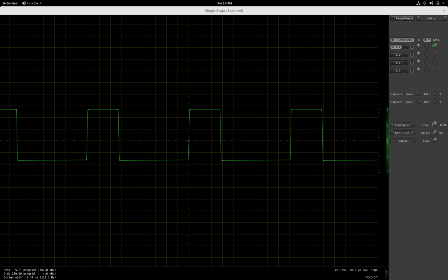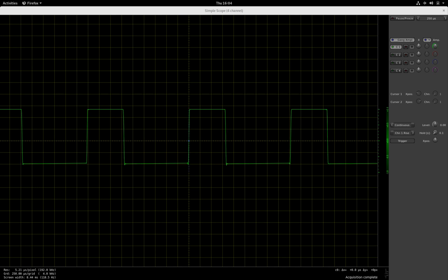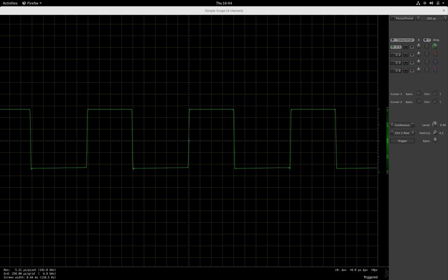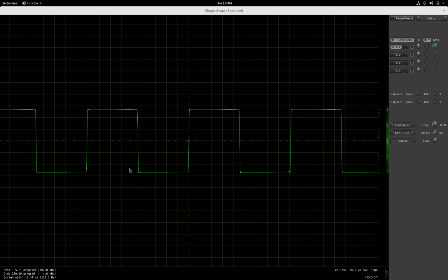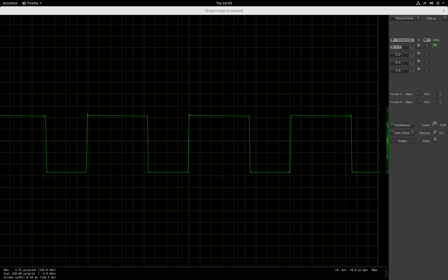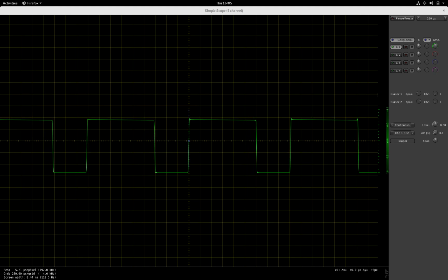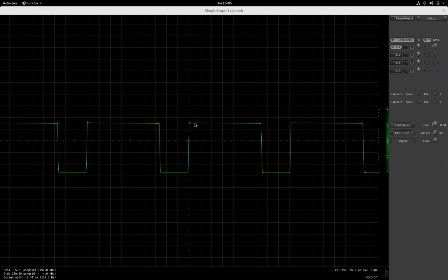And of course we can also change the polarity of the bias voltage, so we will now decrease the bias, and as we move the bias through the 0 point, we will see that the clipping is now symmetrical. So it's basically the same as with the distortion unit, but we can also go negative on the bias. And then we will see that the positive half wave is now long and low, and the negative half wave is high and short. Okay, so it's just the other way around.